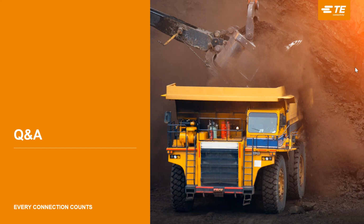The DT high-speed connector is designed for single pair Ethernet connection. Where there's a requirement for a 40-meter individual linkage of Ethernet, you could potentially use it between a cab and a trailer if that is the requirement, but we'd have to look specifically at your application. There are other specific breakaway systems. I don't know if you're looking for a breakaway type of system where the connector would disengage and not be destroyed if there was a separation of the trailer from the cab. We have other products in that range, but it could be used for that type of length of connection for a single Ethernet connection.